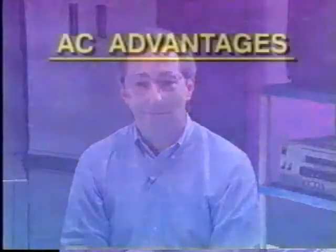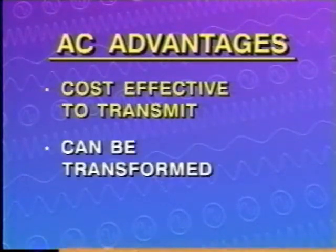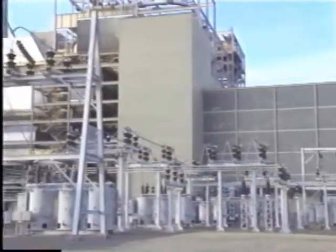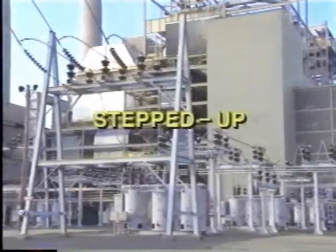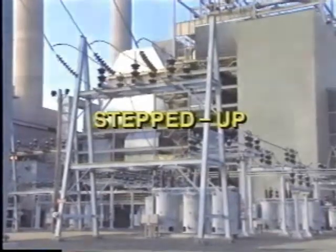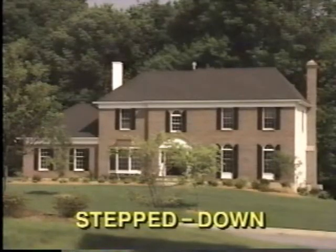AC has two important advantages over DC. One advantage is that AC can be more cost-effective to transmit over long distances. A second advantage is that AC can be transformed to different voltage and current levels, allowing it to meet the needs of many different components in circuitry. Because of its changing direction, an AC voltage can be more easily increased or stepped up for transmission, as happens to the voltage being distributed from a power plant. Likewise, it can be decreased or stepped down before it reaches its destination, such as your home.